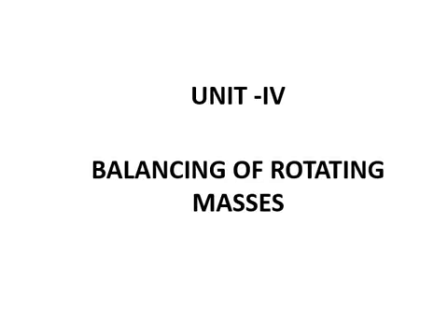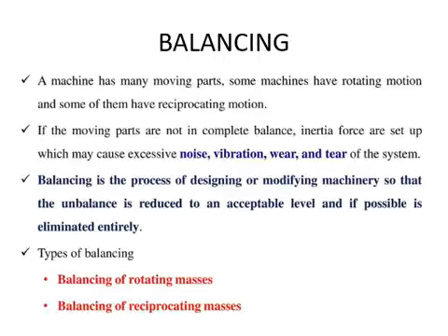So in this unit we will see about the balancing of rotating masses. As we all know, machines have rotating and reciprocating masses. If the rotating and reciprocating masses are not properly balanced, they generate unbalanced forces. The unbalanced forces and unbalanced couples are dynamic in nature.